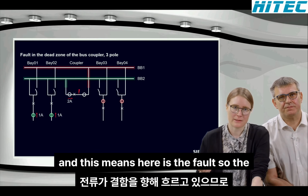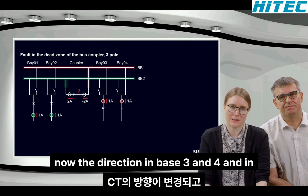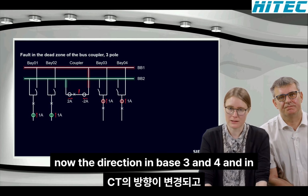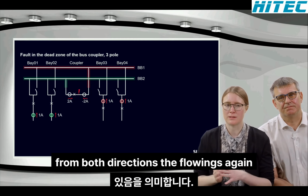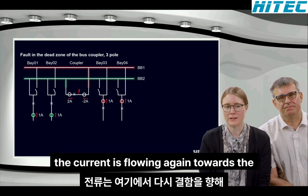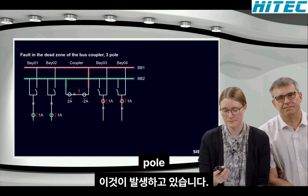This means here is the fault, so the current is flowing towards the fault. So now the direction in bay 3 and 4 and in the right coupler CT changes. And now from both directions, the current is flowing again towards the fault here. And this is happening 3-pole.